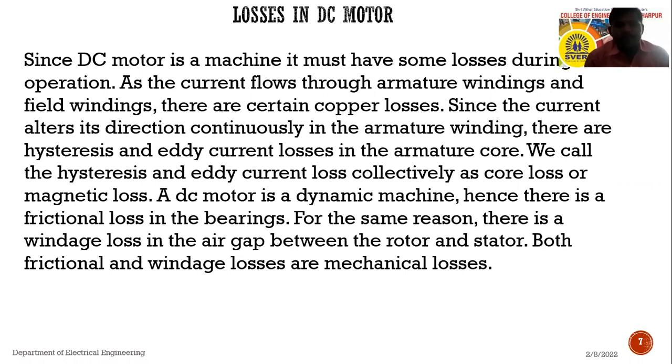Since the current alters its direction, there are again some losses like hysteresis as well as eddy current losses. Hysteresis loss and eddy current losses are present in the armature core. So we call the hysteresis and eddy current loss collectively a core loss.